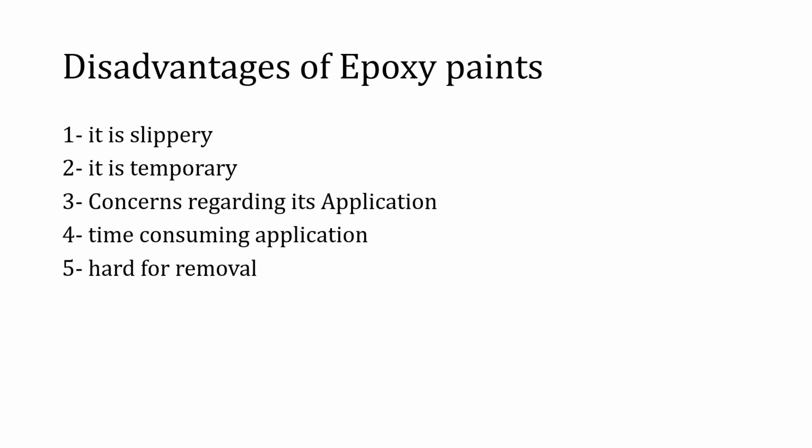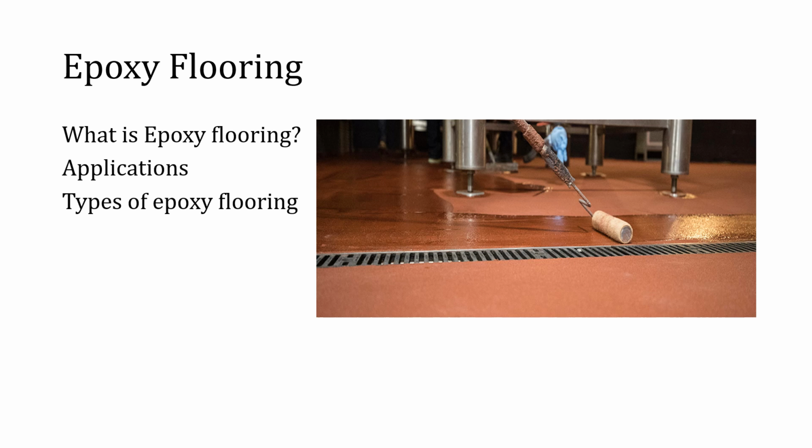Epoxy flooring refers to a floor that has been coated with a protective layer of epoxy. The systems can comprise several layers of thermosetting resins that are coated, troweled, or poured and generally applied on a concrete substrate.